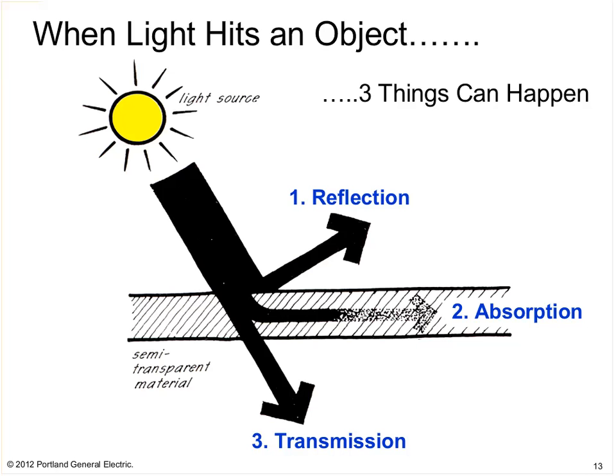So would the color of walls and ceilings in a room make a difference in getting light to the work plane? Absolutely. Light is also going to be reflected off walls and objects in the room. Only some of the light rays reach the work plane directly. Others are going to take a more indirect path. So an energy saving tip is to use lighter surfaces on your walls, floors, and ceilings, and also have more reflective surfaces in your fixtures.